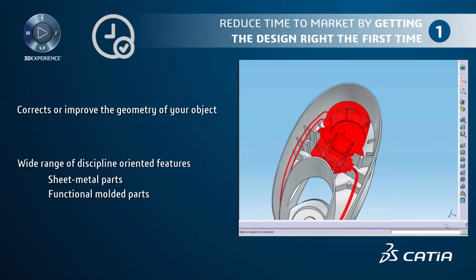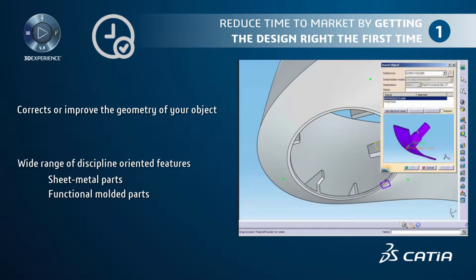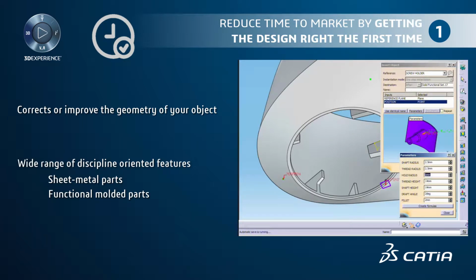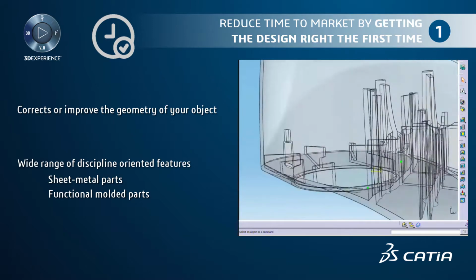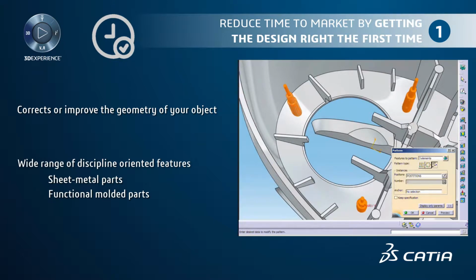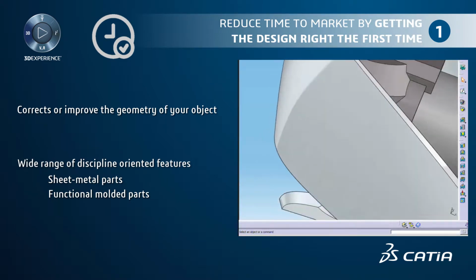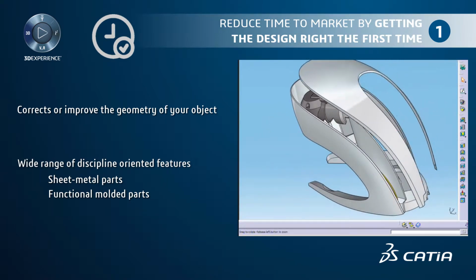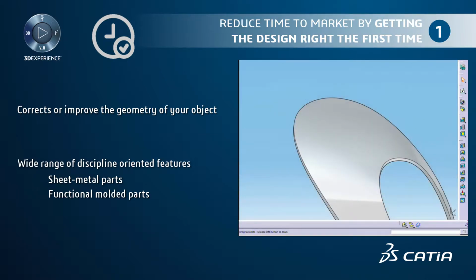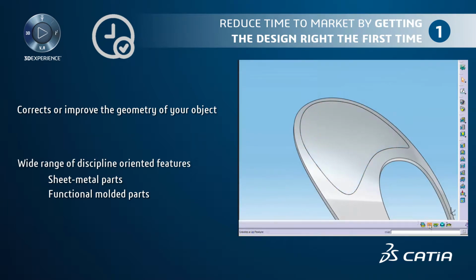With functional molded parts, you can take manufacturability constraints into account early in the design phase and speed up assembly design. CATIA Functional Molded Parts is a product for designing cast, molded, and forged parts and related tooling with unmatched productivity and flexibility. You can add some stiffeners that are automatically relimited on the shell and on the protected area. This approach reduces the design to manufacturing cycle by defining the complete functional specifications for both parts and their associated tooling. Functional molding enables product designers to focus on the functional goals and design constraints of their product.